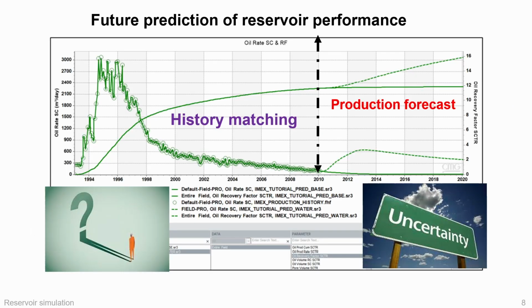Once a model is reasonably history matched, we can use it for future prediction of reservoir performance. This is one of the main reasons simulation is so valuable. We can forecast production decline, water breakthrough, recovery factor, pressure evolution, and the effects of possible development options. For example, we can ask, what happens if we add an injector, drill an infill producer, reduce a rate constraint, or implement an IOR method? The reservoir simulator helps answer these questions before the company commits capital and operations in the field.